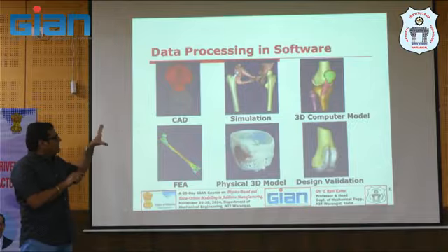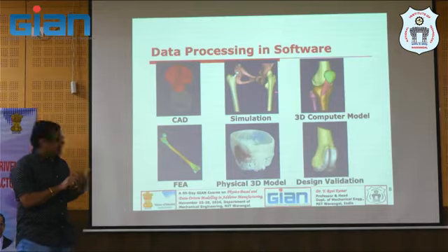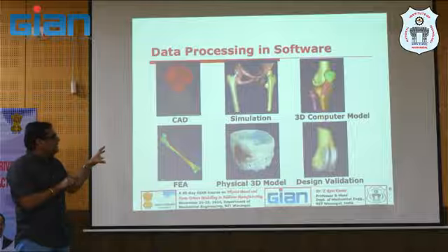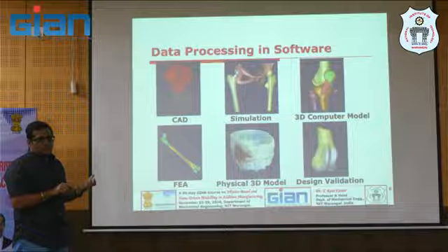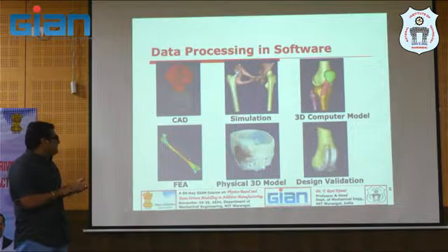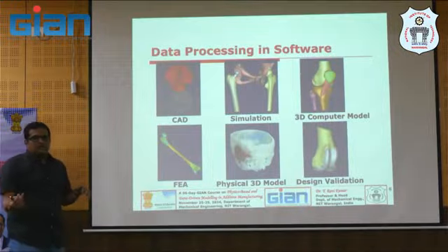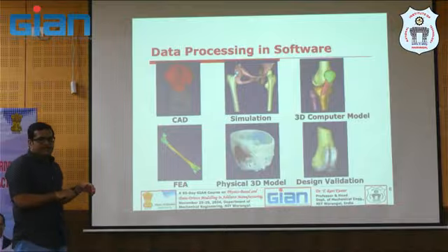You have designed it by scanning the patient data, and before printing it, or before he or she goes to operate, we need to check the fitment of this joint, right? So then you can do a lot of simulation in these kinds of tools, and 3D computer models. So we need to take this data into 3D, or you have designed some joint or implant where we need to test against the maximum load conditions. So maybe you have a femur bone or a tibia bone. So obviously we need to go with the FEA analysis.